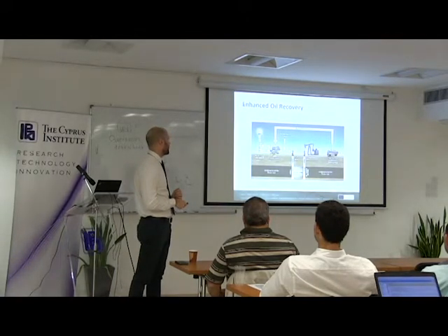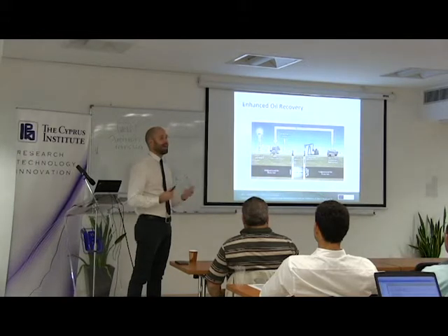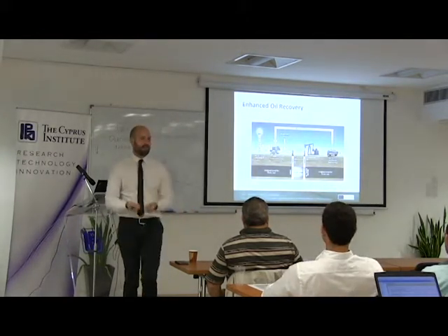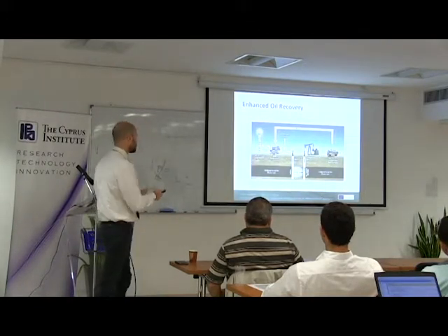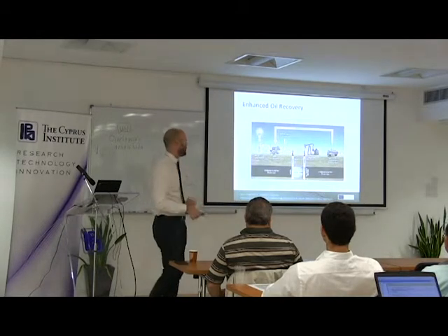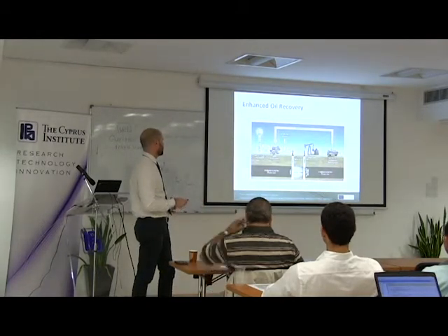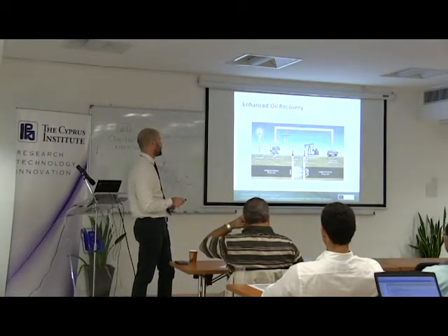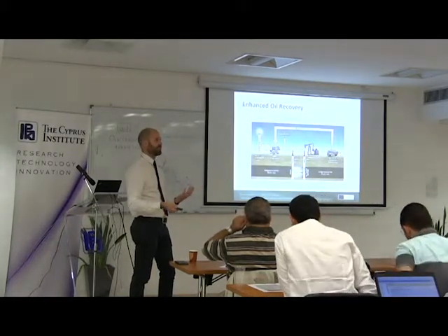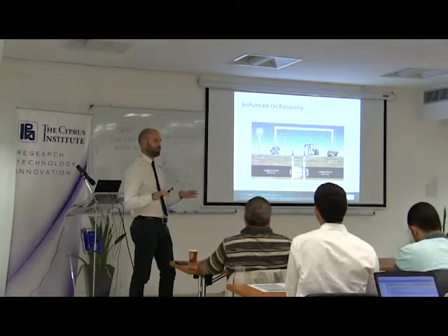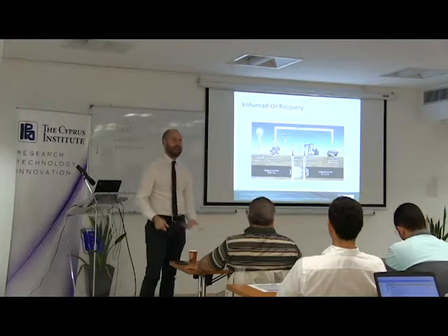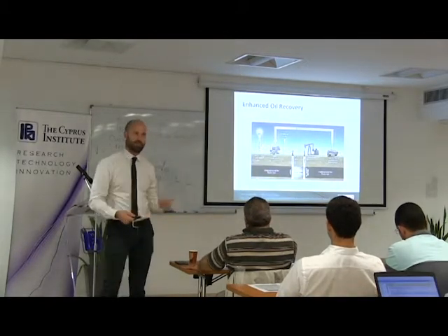This becomes harder and harder as the reservoir becomes depleted, because you are taking the resources from the reservoir. In that case, the pressure of the reservoir gets lower, and this is also why when you produce oil, you're producing also water together with oil. What is done in the oil industry is that you separate water from oil, you treat the water, and you inject the water back in the reservoir to enhance the extraction of further oil.